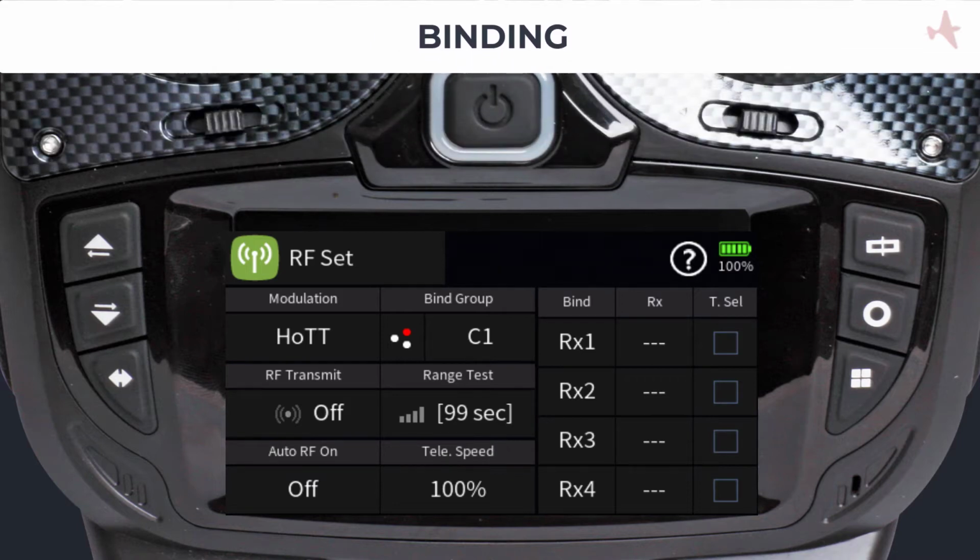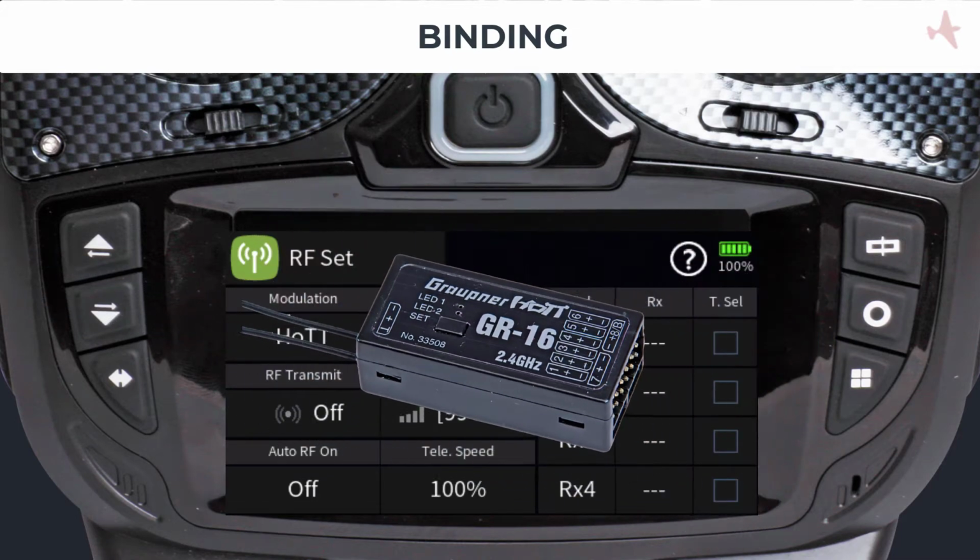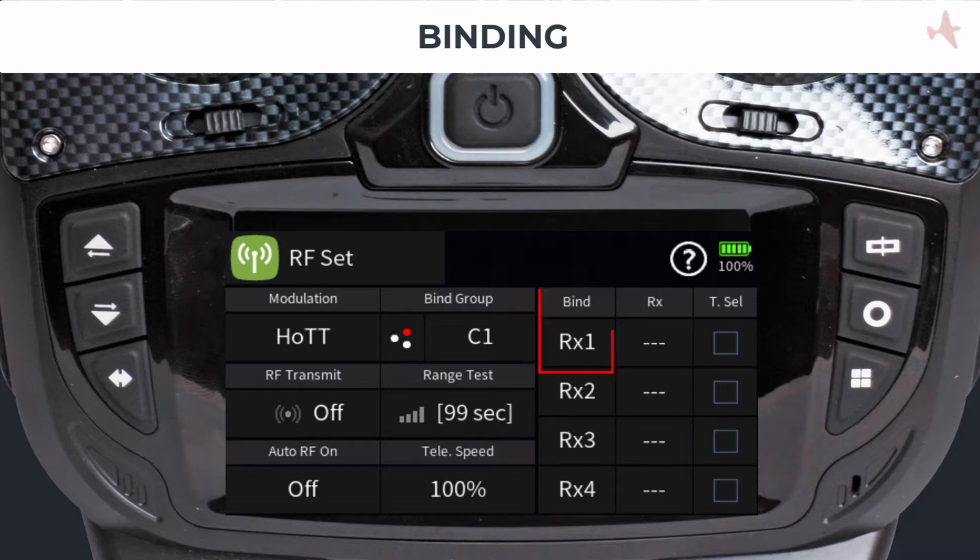Depending on your radio model, you can bind up to 4 receivers to your model. The binding process requires you to place the receiver in bind mode. This is done by pressing the Set button on the receiver, and after 2 to 3 seconds, you can tap the Bind button on the radio. You need to bind RX1 first.